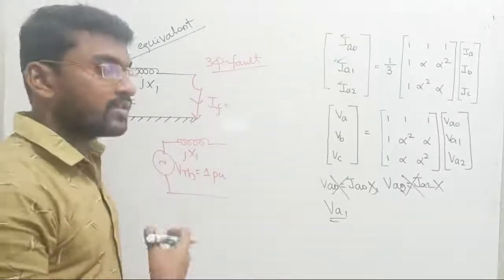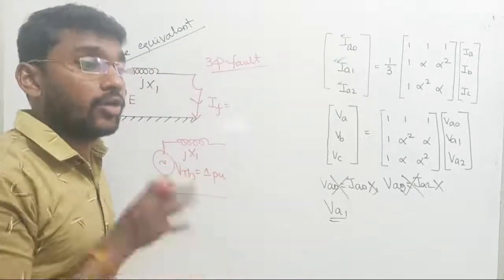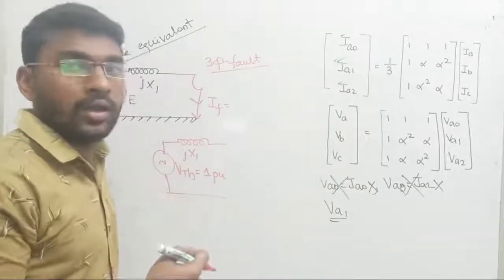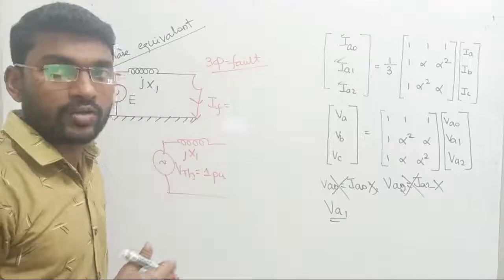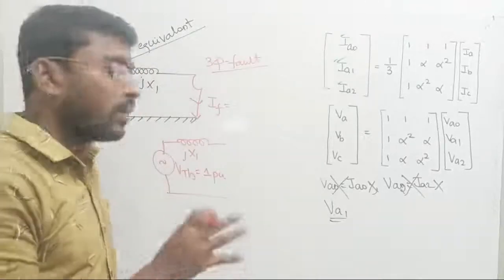So the assumption is, right, prior to the fault our system was connected to no load. The assumption is that before the fault happens our power system was directly connected to no load only. It does not attach to any type of load in our system. That is the assumption to get the worst case current, the worst value of fault current.